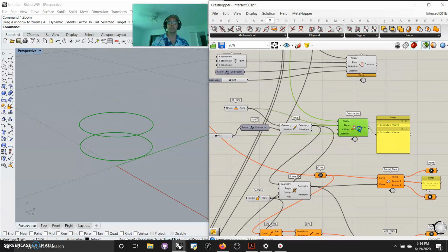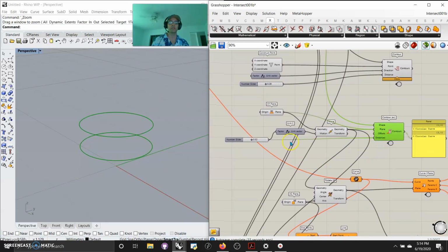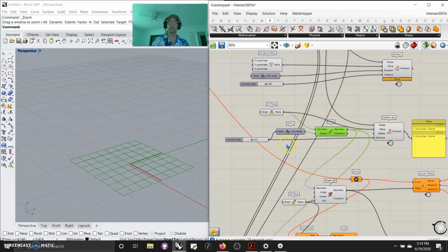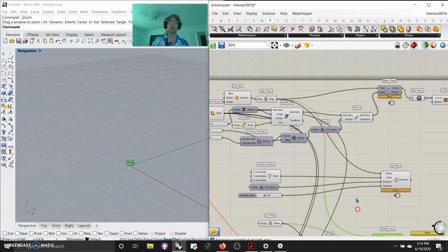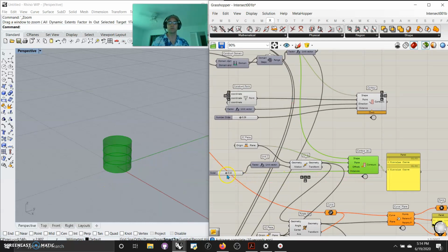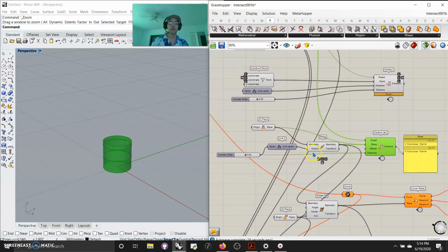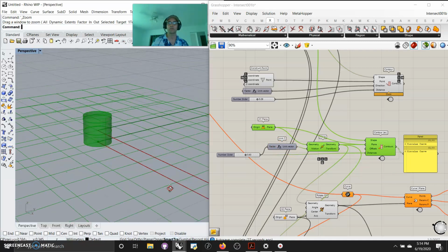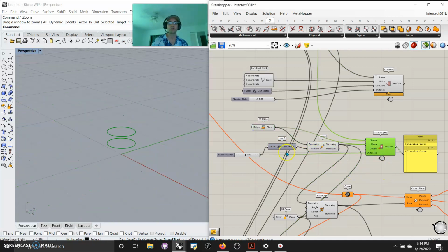Pretty cool little tool. If we grab in there, you have a lot more control over the offset or distance. What I'm going to do with that is grab that plane and offset it at a different height. So not only do we have that initial Brep point, we're going to come back up to there. We're going to want to use that to offset the distance. You can do offsets or you can do distance. It doesn't really matter. But you have two curves here because I took one plane and brought in two. The reason there's two splitting here is I took the initial plane and then I also moved that plane. So I have it in two locations, and having it in two locations gives me two lines. So that's why I end up with two. That's a subtle little thing just to play with in the script.